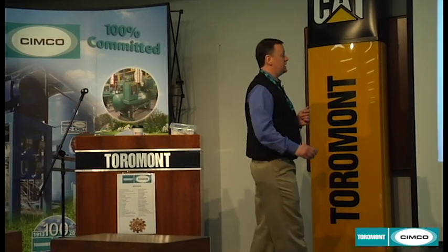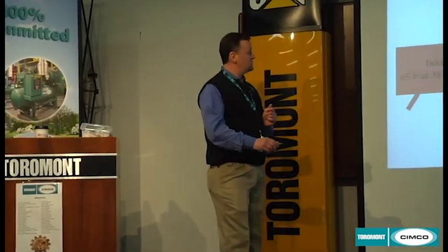Now, with this technology, we can achieve, and this is a pretty typical return condition from an ice arena, 65 degrees, 30 grains, that's a 35-degree dew point. We can achieve pretty readily 0 to 10 degree F dew points coming off of these wheels. So much lower dew points delivered to the space allow us to get much better control of the humidity within the space, and we certainly can achieve 35 with no problem.